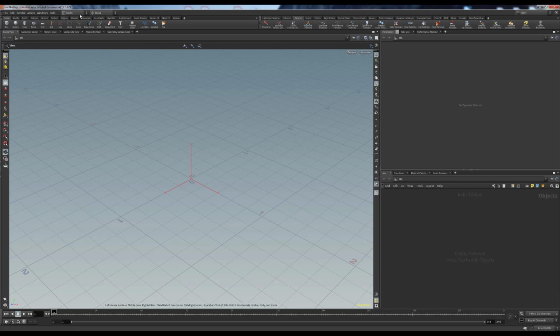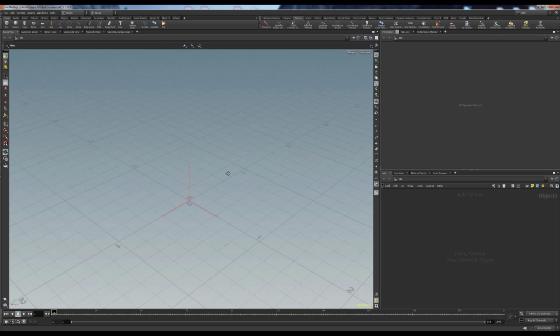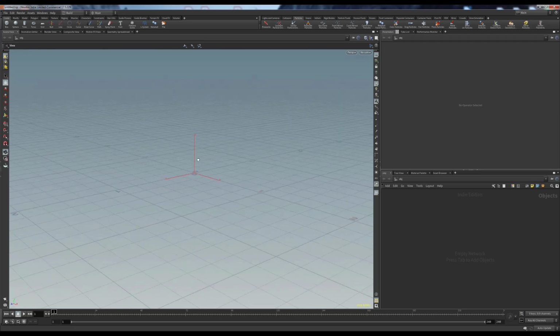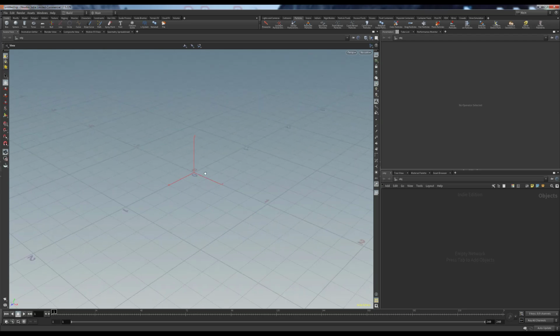We are going to use release 17.5, and our first idea is to start playing with fluid dynamics. So this is the 3D view. To move inside the 3D view, remember that we can use the middle mouse button to pan, Alt key and left mouse button to orbit, and Alt key and right mouse button to zoom. This is just the beginning to start playing with the scene. The unit of measure is meters, so for example, this one is 1 meter, 2 meters, etc.